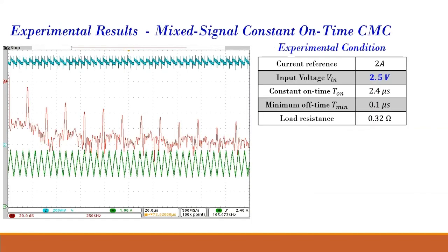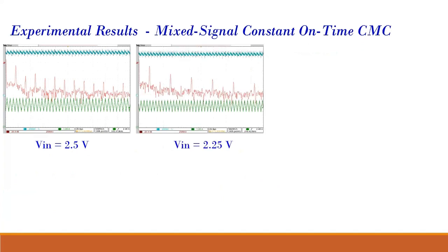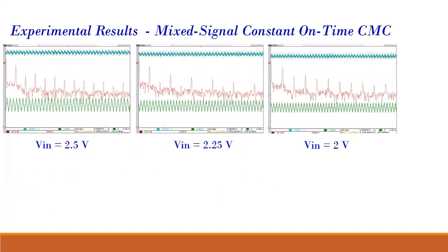And these are certain experimental results. This is the valley current, I valley, and that is set at 2 ampere. 1 ampere here, another 1 ampere here. That is why my current is always reaching the valley reference and turning on. And this is shown for different voltages. If you observe, there is no instability. It is always like this, not of the form like this, like this.